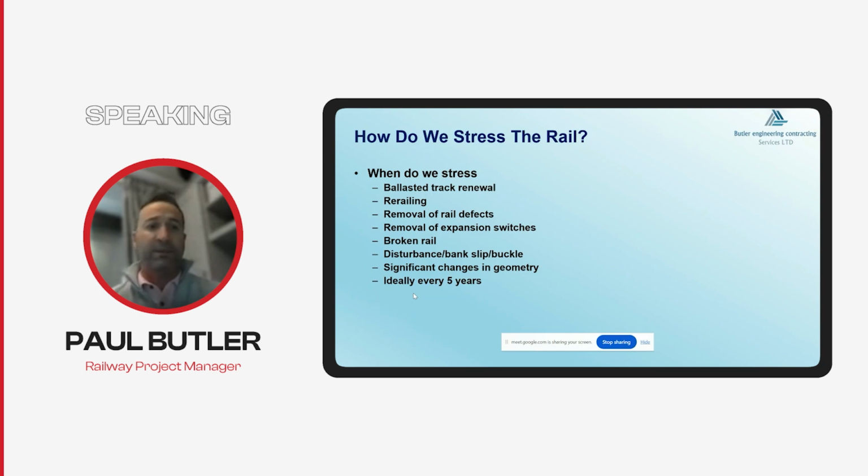And ideally, in an ideal world, you'd re-stress your track every 5 years, although I would imagine around most of the world, this rarely occurs, and from a budgetary point of view, is very, very challenging.